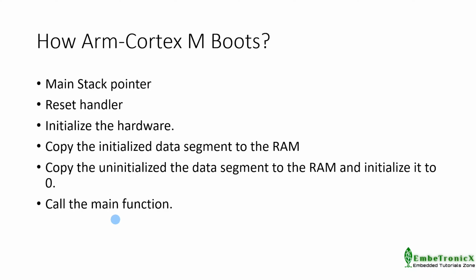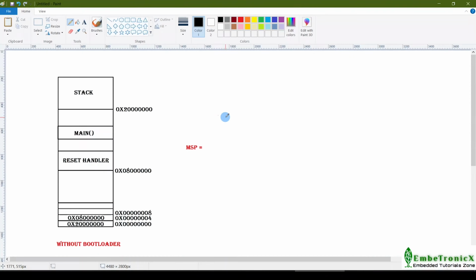Okay, we have a basic understanding of bootloader. Now, we have to know the booting process of the microcontroller. What happens when you press the reset button or power up the ARM Cortex M4? When you press the reset button or the microcontroller powers up, the PC is loaded with the value of 0. Memory 0 will have the stack's starting address.